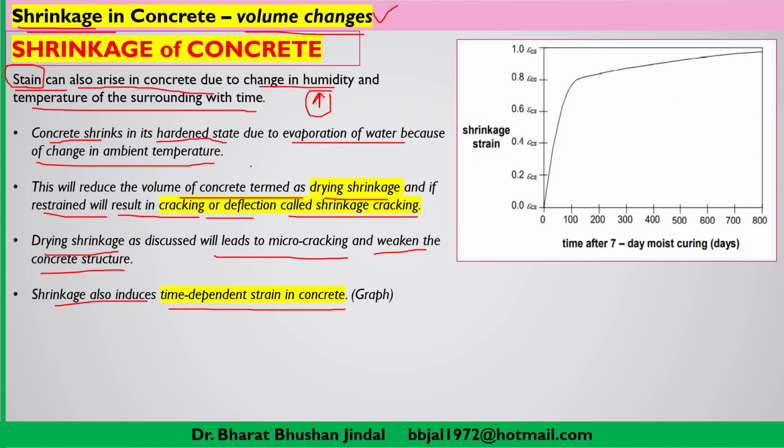Now you can see here along the y-axis it is shrinkage strain, and along the x-axis there is time duration. Now this time is calculated after 7 days of moist curing. So from this graph it is clearly visible that as the time is increasing, shrinkage strain is increasing.